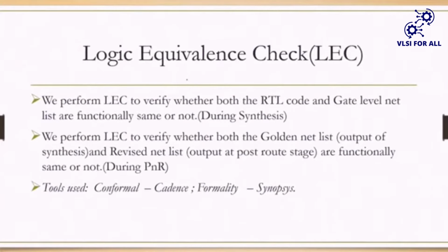Let's consider synthesis, because I told you in physical design the first step is synthesis. In synthesis, the RTL team's HDL file is the input, and the gate level netlist is the output file.